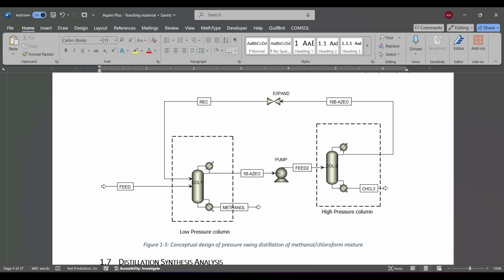Everybody got it? So at least for the binary analysis, we can first judge whether the thermodynamic method is suitable for that system, and that can be checked by comparing the experimental data obtained from the NIST thermodata engine with the simulated data. We can perform the simulation with lots of different methods and cross-check. If the simulation mimics the actual behavior of the experiment, that means that thermodynamic method can at least mimic the two-phase behavior, and that is appropriate for the given system.